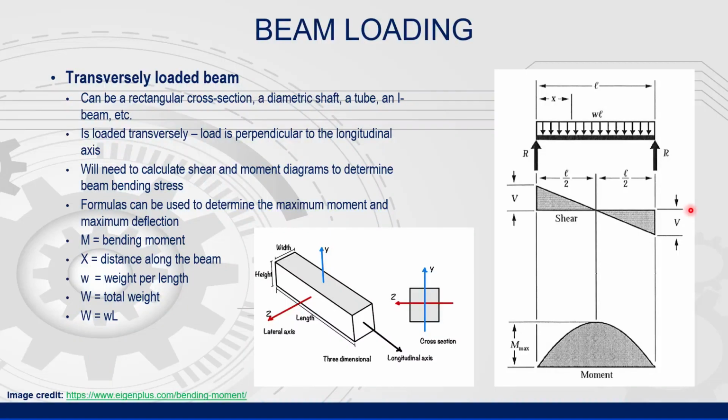Below the free body diagram is the shear diagram. This represents the shearing loads applied to the beam. Variable V is the shear force, not stress. In some setups, the shear force V is equal to the applied load, W or P as the case may be. However, for a beam setup like this one, V is 1/2 the total load and equal to the reaction at either end.